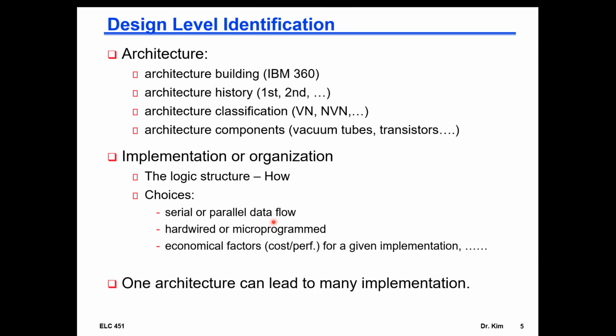They are just there to implement that instruction that is visible to the user. That's a way of doing control. Another one is what is called hardwired, which really is a state machine. So when you see hardwired as a way of implementing control, you're talking about a state machine. However, it becomes very complex. You have so many states that it becomes almost unmanageable. So at some point, you have to go to this microprogram implementation.